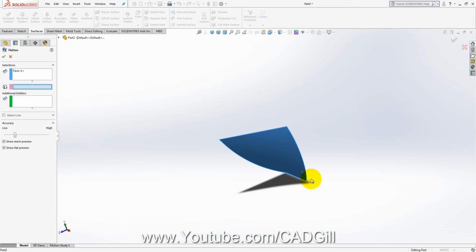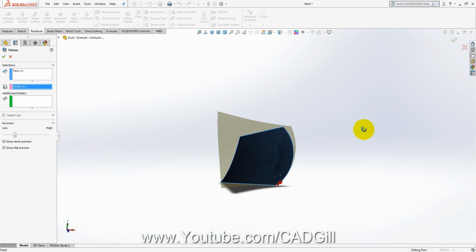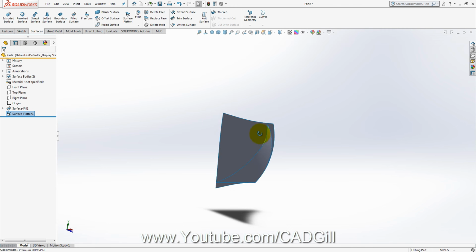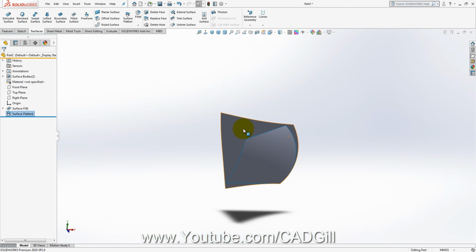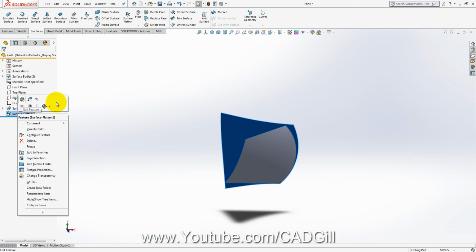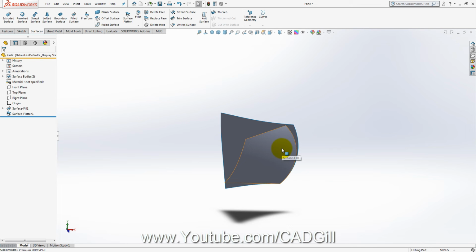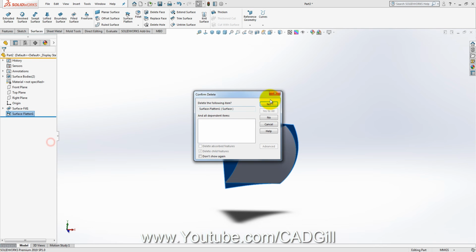But it is used to flatten the surface, and you can use that area for multiple things, like area of a piece of cloth, but never assume the case of cloth because the name implies solid. You can see solid, it doesn't say cloth or fiber or anything. It doesn't support these features. Or you can use this feature in sheet metal, where you have to calculate the surface area of a complex geometry for blank calculation, etc. Okay, so surface flatten, and delete this.